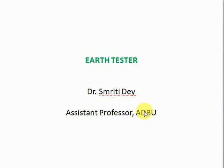Because our earthing, we pass it to the ground, and if the resistance of that ground or the earth is high, then the fault current will not pass through the earthing. That's why we need to measure the earth resistance, and that resistance should be very low for earthing. And here today I am going to explain the construction and the principle of an earth tester.